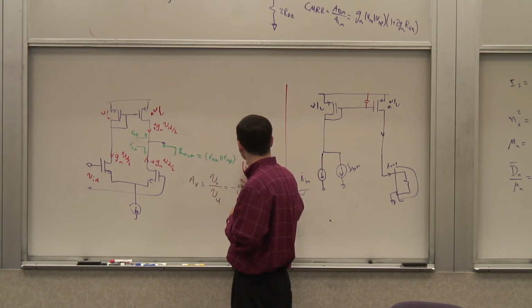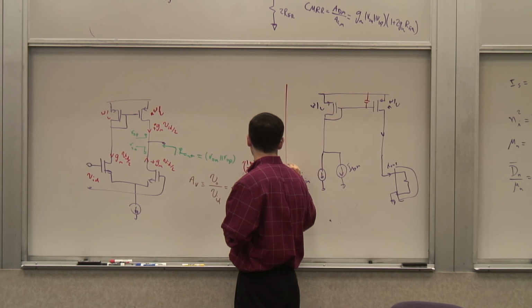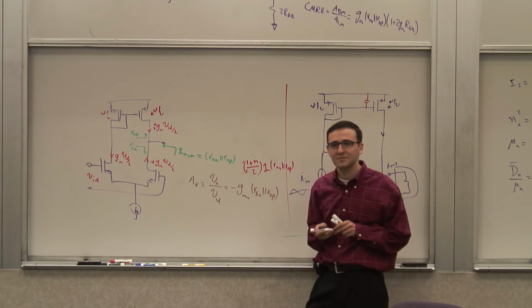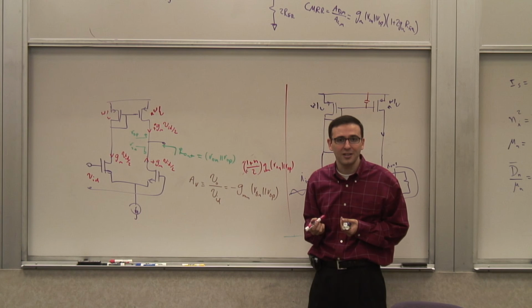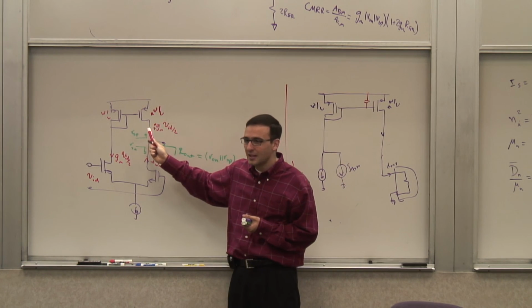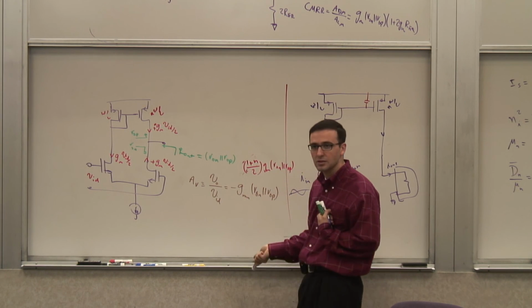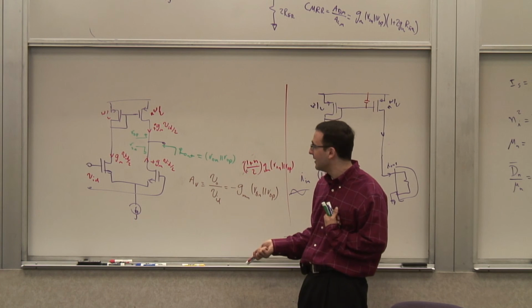1 plus N over 2 times Gm, RON in parallel to ROP. Right? You could do that, right? I'm getting some additional gain here. And this half gets multiplied by N. If you set N to 1, that reduces to this old result. And it does do that.